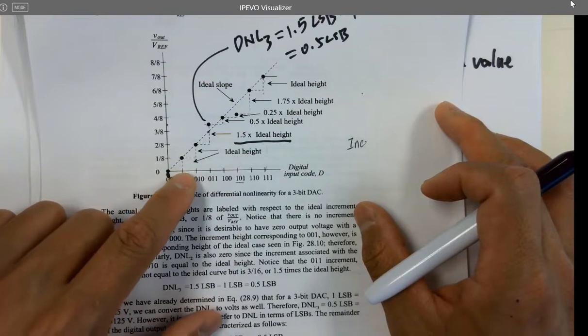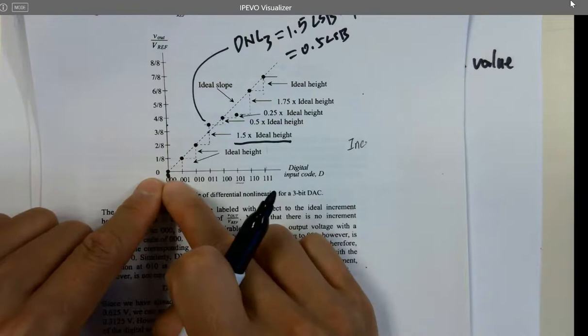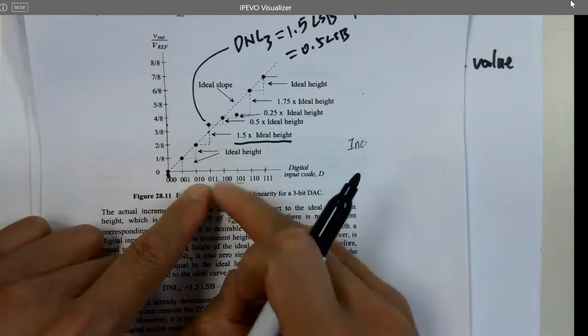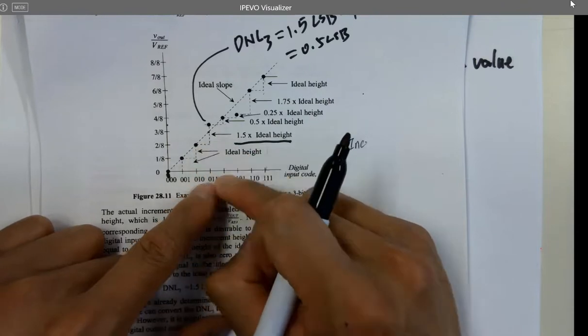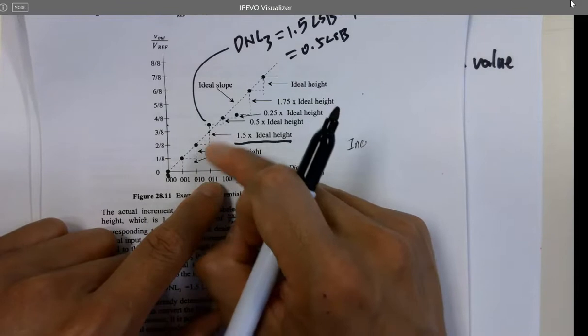That's an increment. Is that 1 LSB? Yes, no problem here. See, that's one step up, which is 1 LSB. Jump to here, there's another increment. It's still a 1 LSB increment. What about this one? So the DAC is not doing a great job.